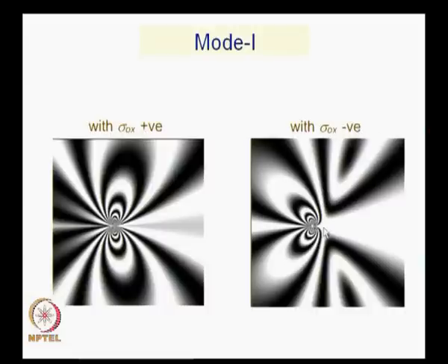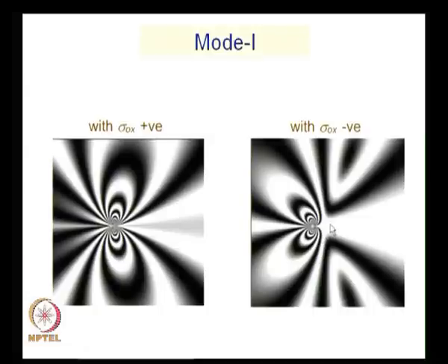So, here I have cracks tilted backward, and this kind of situation is seen in the case of a different type of specimen known as rectangular double cantilever beam specimen. We have already looked at the double cantilever beam. We had very thin top and bottom portions. Suppose I have that broad enough and I have a specimen long enough like this.